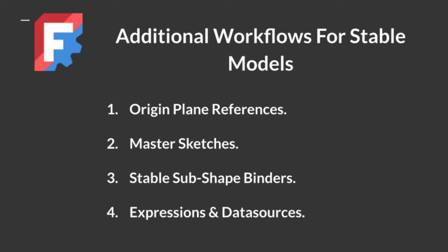The following approaches focus on building models on a more stable foundation, starting with a stable reference and progressing to master sketches, which capture the essential geometry and design intent. We'll look at such methods as referencing the origin directly, the master sketch workflow, tips on using ShapeBinders and using expressions, varsets, and spreadsheets.